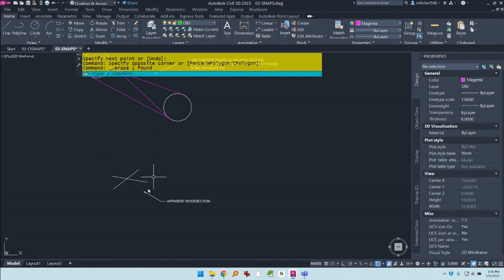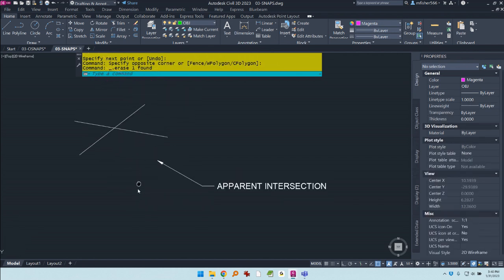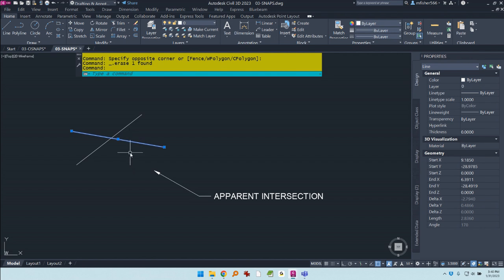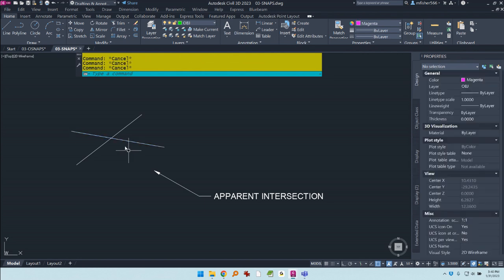All right, this one takes a little bit more understanding here. So it looks like these two lines are crossing one another. However, if we look a little bit closer, what you'll see is that this line has an x, y, and z value, particularly the z is 0 at the start and the end. That means it's down in what I'll jokingly call flatland, okay?